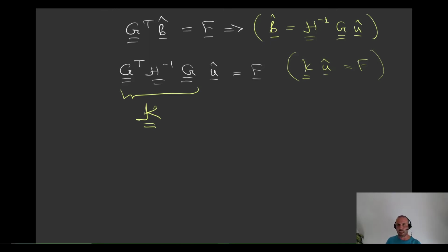And important is to note again, what have we done actually? Why did we even go ahead and derive these equations? The initial thought we had is that we wanted to apply the condition with respect to the shear deformation, gamma, which is equal to W prime plus beta, weakly into our system, aiming basically that the resulting system of equations is not going to suffer from shear locking, right? Because here we applied this equation weakly.